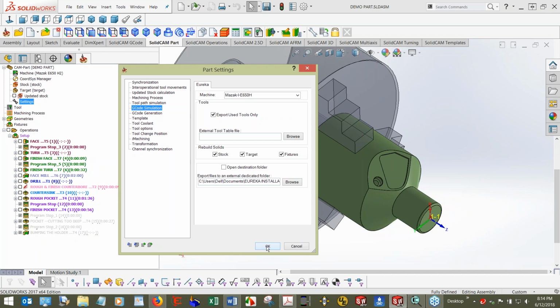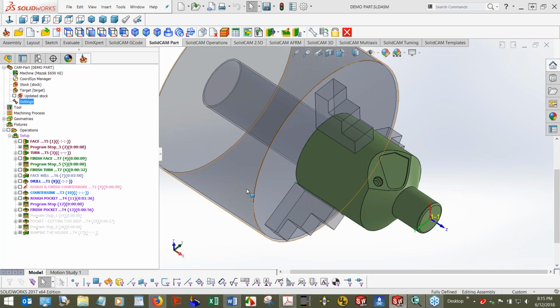So in all, just for Eureka, the only thing you really need to set up is just a G-code simulator, because we've talked in a lot of the night classes about adding the setup and putting that fixture in there. You guys are all used to doing that portion of it. The only thing additional would be putting that Z dimension in there on how far that part is from the spindle. So pretty easy, simple so far. Yeah, and if you have a lathe already set up, you probably would already have your chuck in there, and you may just be sending your jaws with your part. So you would just attach that.